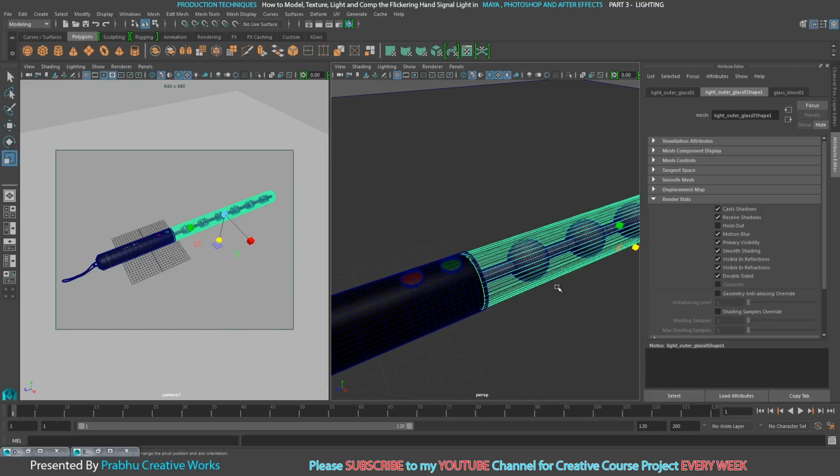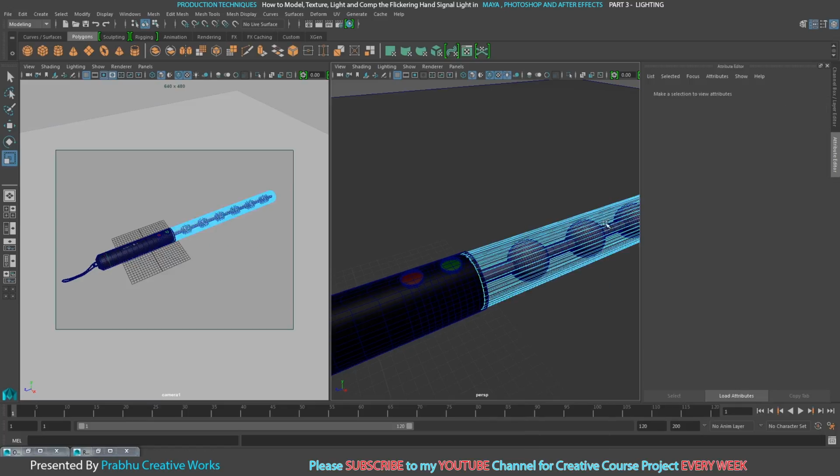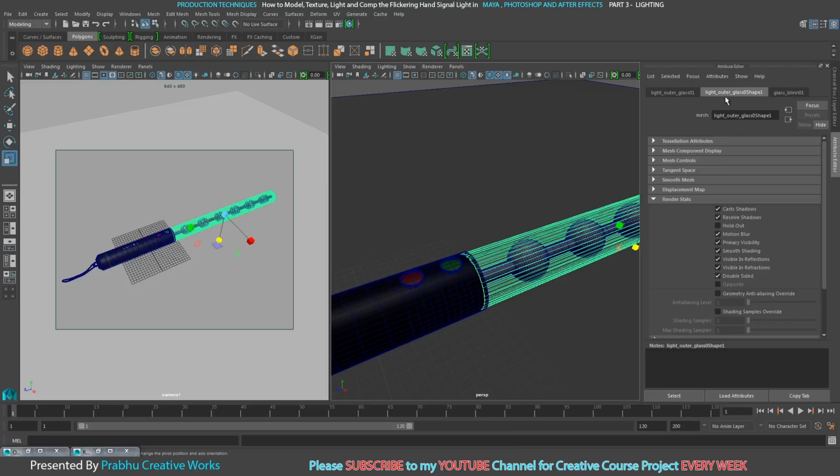click this object. So if you have any glass material, you definitely want to turn off cast and receive shadow. Because in nature the glass material cannot cast any shadows, so I will select this object and go to this object settings in attributes. So light outer glass shape 1 and disable the cast shadow and receive shadow.